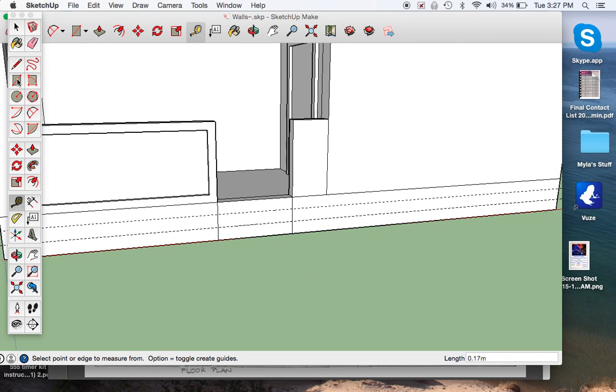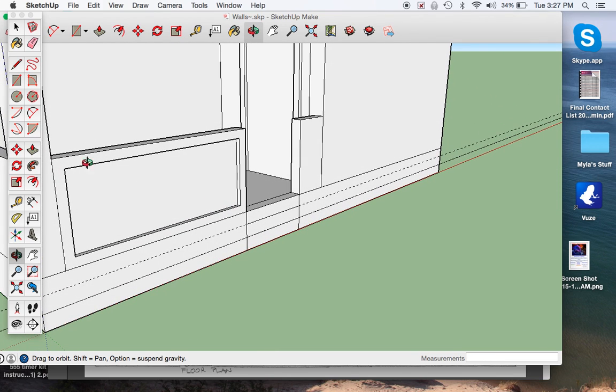And then you can make a little rectangle there. Drag it out. I think you seen this on another video. Alright, and then you can extrude that outwards. Now this is called the rise of the steps. It's just the step up. Alright, you don't want it too high. You want to make them even steps all the way up. Otherwise you kind of stub your toe or you trip over it because your mind subconsciously knows the height of steps. And then you have what is called the run.